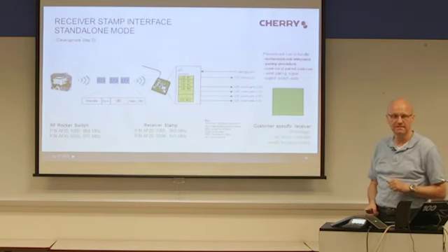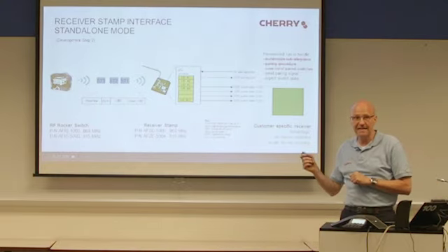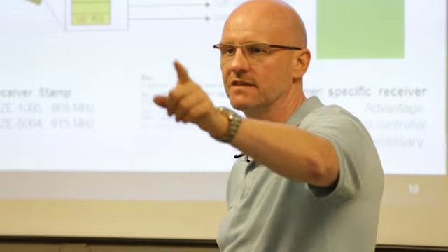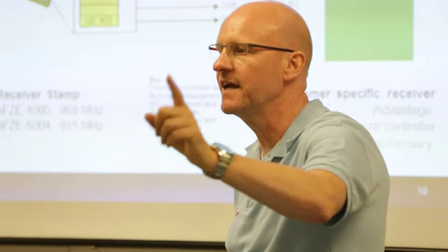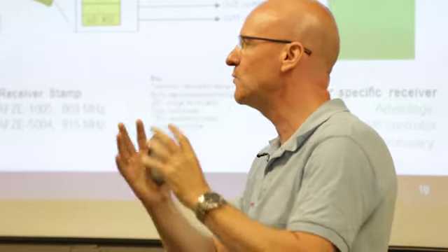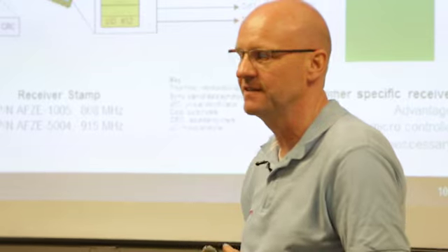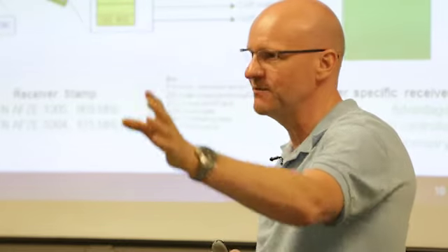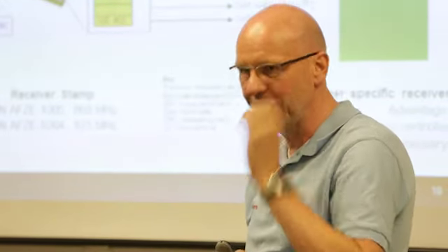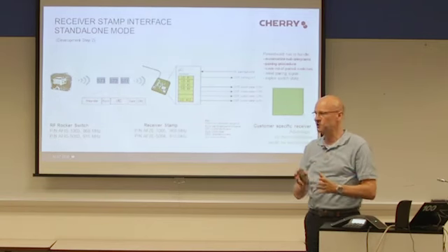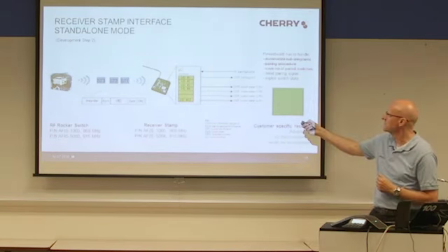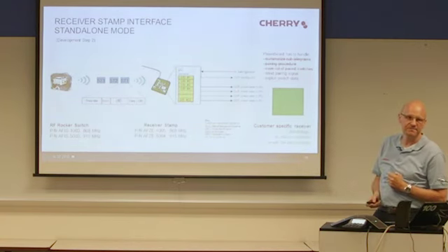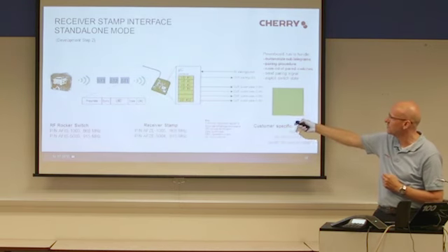Switch is pressed. The receiver doesn't have to know if it is switch 17. He only has to know: a switch which is paired with me sent me a press, and I have to switch on the light. It does not matter if it is switch 17 or 18. It's a paired switch, and I have to switch on the light. And this is important because he doesn't need intelligence. He only has hardware outputs.